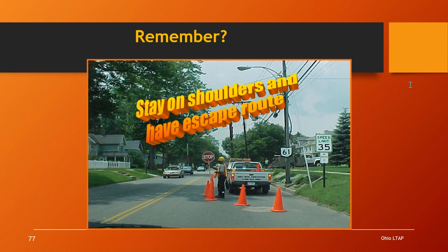Okay, Ray, what do you suggest for a moving work zone, as in stringing cable? A mobile work zone has its own typical application as well, and a different section in the temporary traffic control manual. If you're on a mobile operation on a 2-lane road, that would be typical application number 17. So you need to read all about that. And plus, I have a RON update that you can check out under our resources page of our LTAP page. I did a RON update on mobile operations on 2-lane roads. So that should be pretty helpful to you as well.